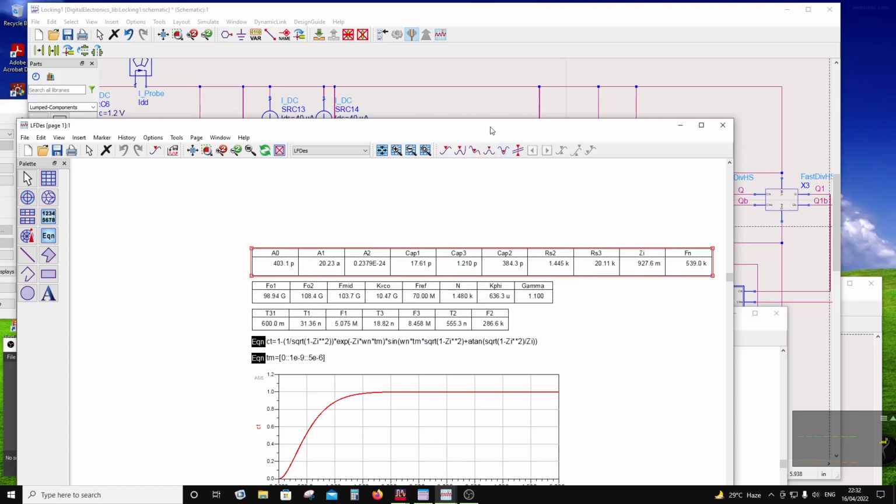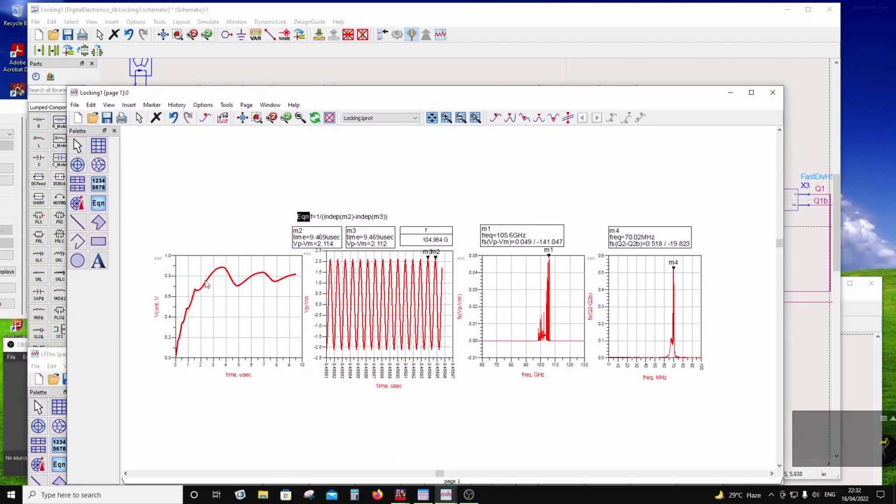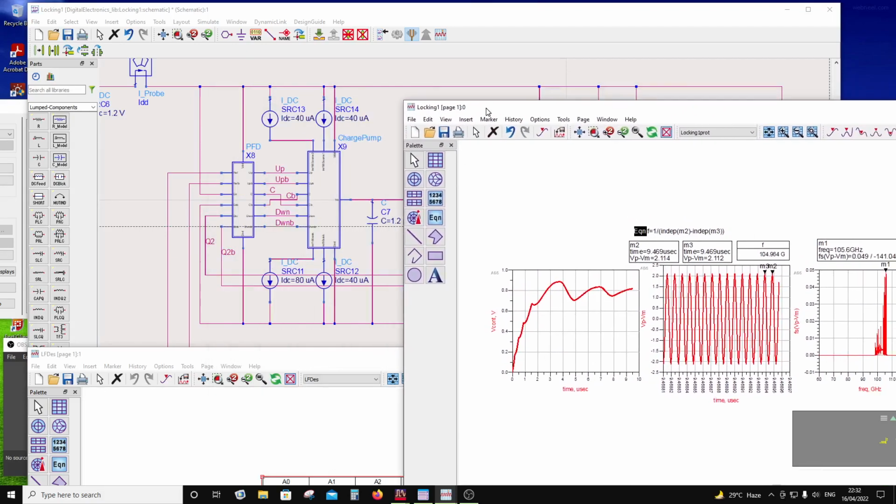That translates to each cycle being about 2 microseconds. So I have to simulate this for sufficient time for this cycle to die down to a constant. The simulation is going to be very lengthy, because you might have to simulate for like 20 microseconds for this to settle, but then you have to time step it as per 100 gigahertz. If you are doing a transient simulation for a PLL to simulate the locking, you have to simulate for that time, and actually you have to simulate as per the sigma delta.